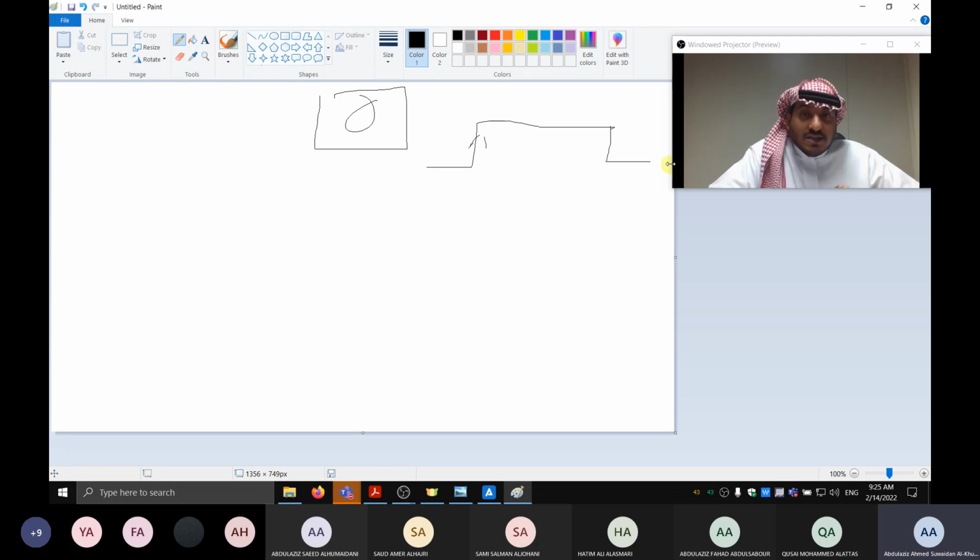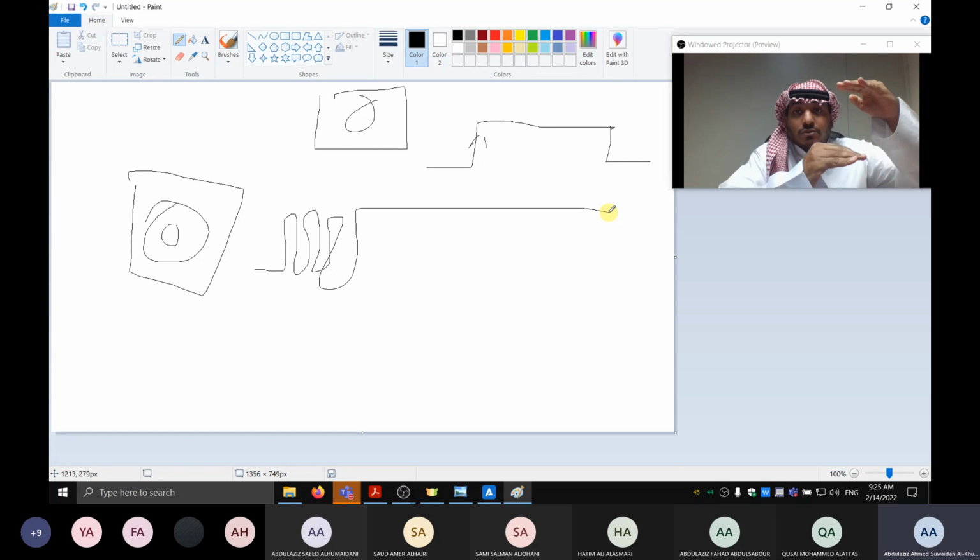That's the ideal case. But in real life, if you press the button, there is something called bouncing. With the two metal contacts, when you press the button, there is a chance, in physical terms, that it will bounce. Like they hit each other and then bounce, and then bounce again, and then it goes to complete conduction. So there is a bouncing issue. They call it bouncing issues if you press a button. This is information for you.